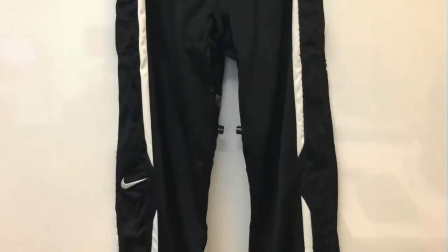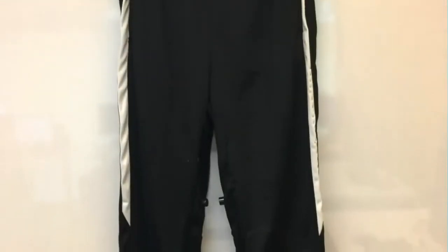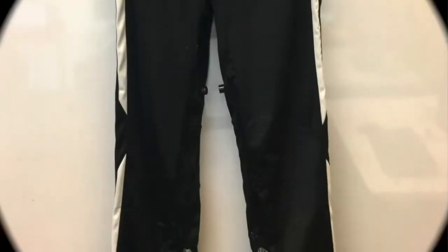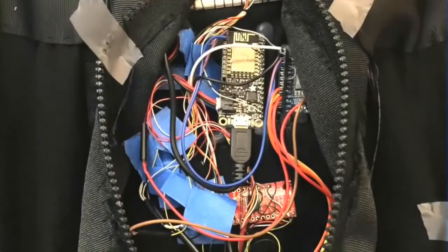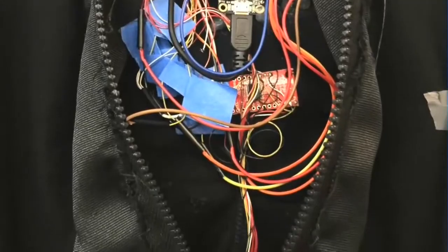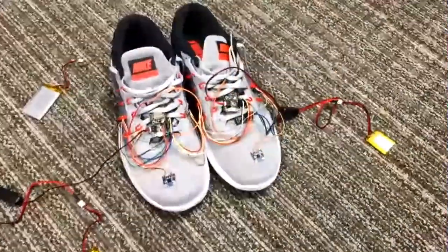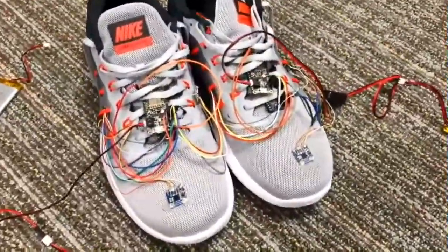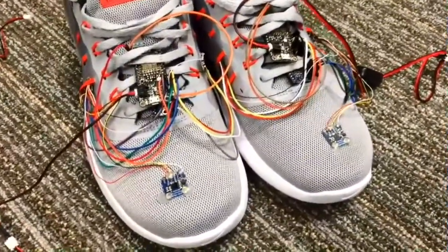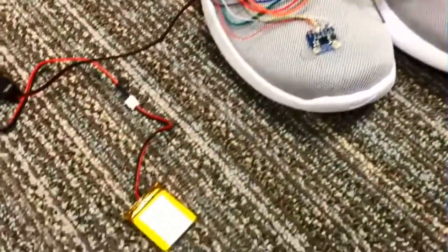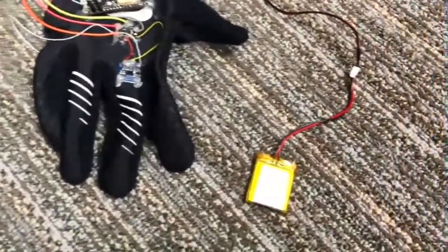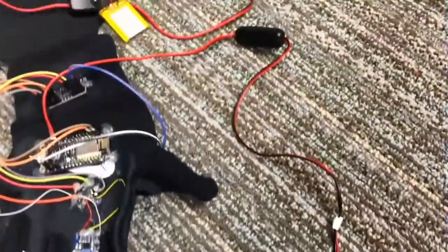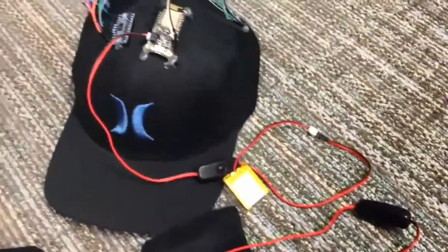On the pants, there are 8 IMUs and 8 infrared sensors. IMUs cover the lower and upper leg while the infrared sensors face each other in the middle. One CPU with a Wi-Fi module is located on the hip part of the pants, since it is the most stable position during motion. For each shoe, one CPU is connected with 2 IMUs and 1 infrared sensor. 2 IMUs are located at 2 sides of the shoe, and the infrared sensor is on top of the toes. An independent battery powers all electronics on one shoe. Same as shoes, gloves have their individual CPUs and batteries. There are only 2 IMUs on the hat, no infrared sensors.